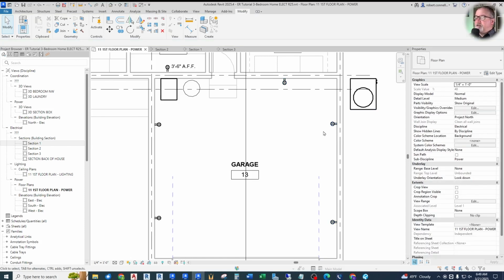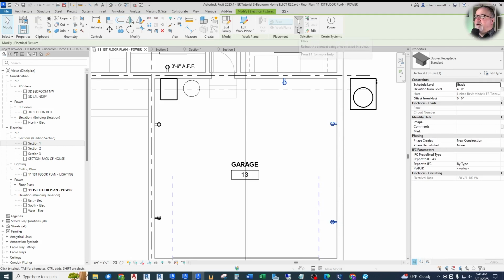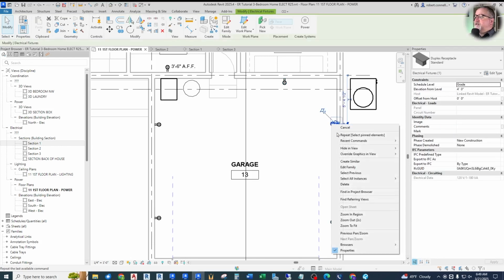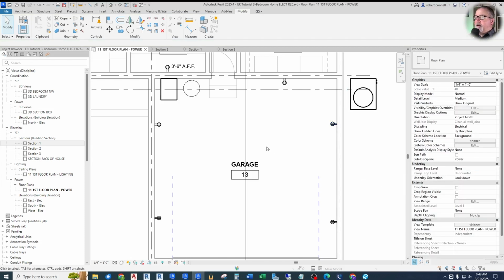There's many different selection tools in Revit. One of them I did show you earlier was this whole filter idea right here, the filter. You can also right-click on an element and say, select all instances visible in the view. Now, they don't mean this window that I'm windowed in. They mean the entire view, so the entire first level floor plan. Or I can go all of them in the entire project that are this type. And then furthermore, you can even include legends if you have things in legends. So you can use these tools to help you select items.